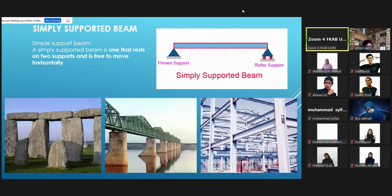And for these two photographs, basically it is a typical bridge structure, how they actually join and link all the bridges together through many continuous supports. But in the continuous support, in fact, these are so-called bridges, they are all independent on their own. They are not connected. Because the connection is only through the column. So if you take one column, two columns, they become what they call simply supported beams, because they don't join together.